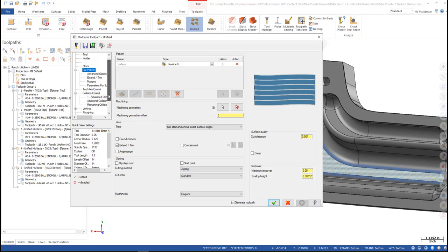And then, like I said, if you want to utilize that extra cut around there, that's going to be an option also for you to turn that cut on to go around the periphery of your cut, eliminating all them little scallops that are potentially there. So definitely check it out and see if you guys can utilize it on your multi-axis cuts.